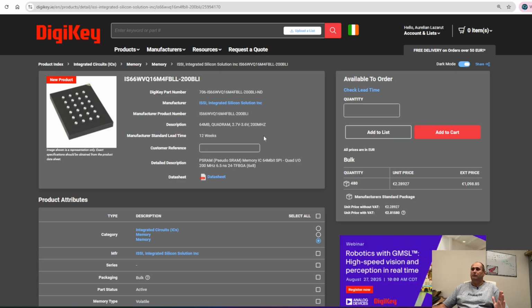But first, pins. I have only 8 pins available. PSRAM in a quad RAM interface seems like a good choice. Now I realize this is going to sacrifice the bandwidth, so that's why I went searching for something which can transfer DDR. When I say DDR, I mean it can transfer on both edges of the clock. This will double the bandwidth. So the information is going to travel between the FPGA and this memory DDR, double data rate, so it will transfer on both edges.